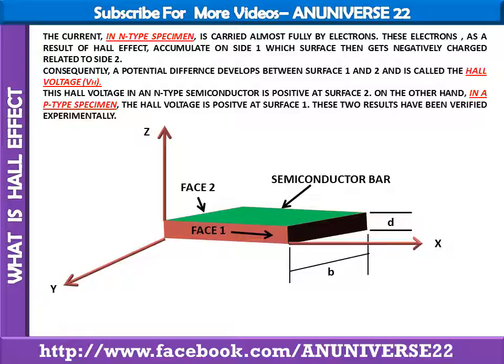The instrument gives an output proportional to the product of two signals. Thus, if current I is made proportional to one input and if B is proportional to the second input, then Hall voltage VH is proportional to the product of two inputs. So this is all about the Hall effect. What is Hall effect and how it works.